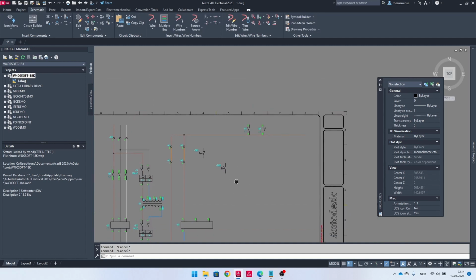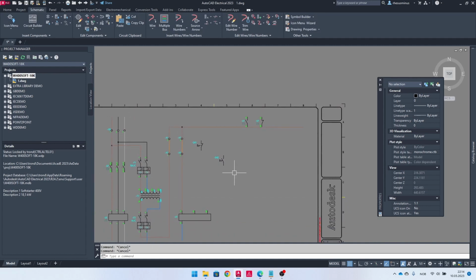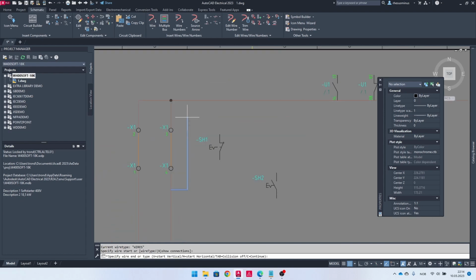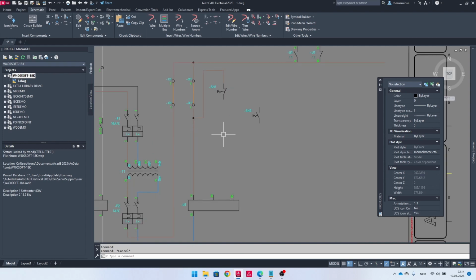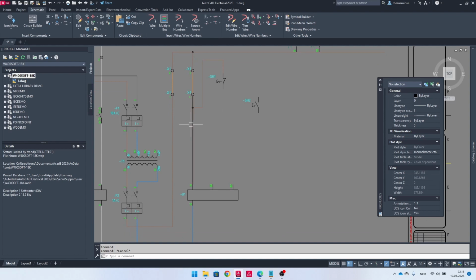These also have lamps, so I need to put these in a little while as well. So this one could get its power from this one here. I'll just move it up here and over here, like this. Then this signal will go down to the terminals. Okay, terminals 5, 6 and 7 for the remote that are also jumpered, of course.